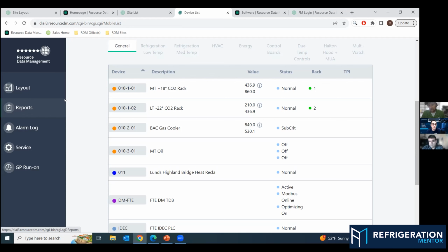Just like Cody said, it could be a sensor. It could be a temperature probe. It could even be a parameter. Maybe it is a controller thing, but the chances are, if it was already running for 6 months or a year, it's not the controller. It's usually a mechanical issue that's causing the problem.